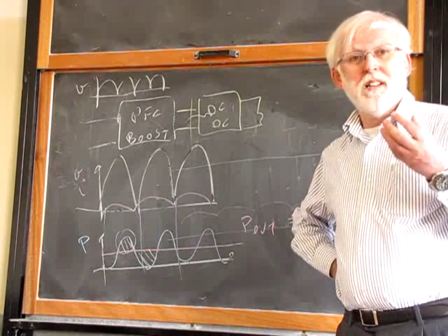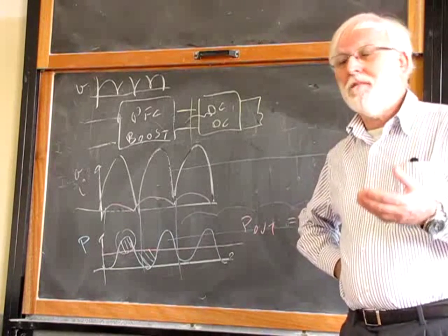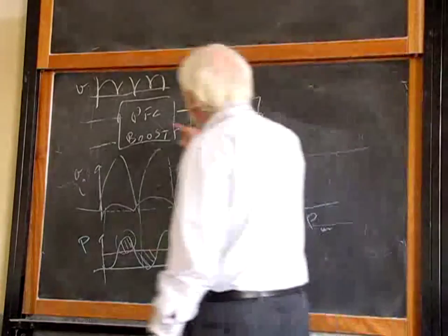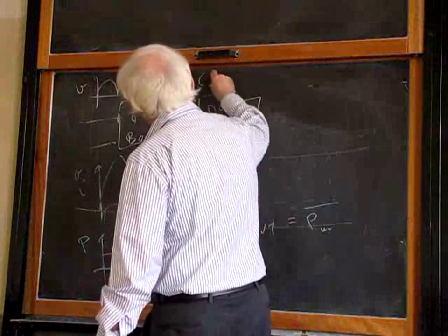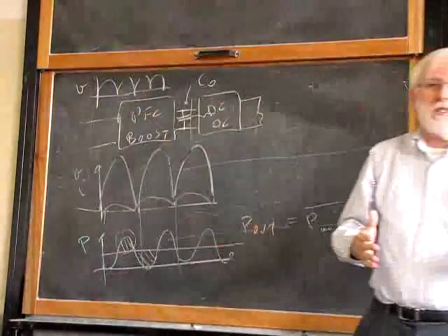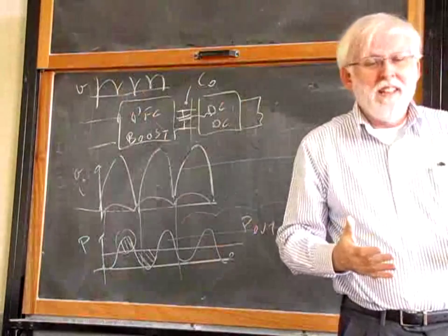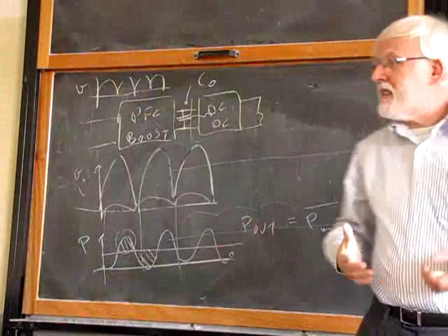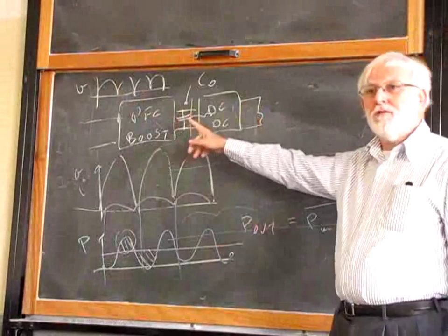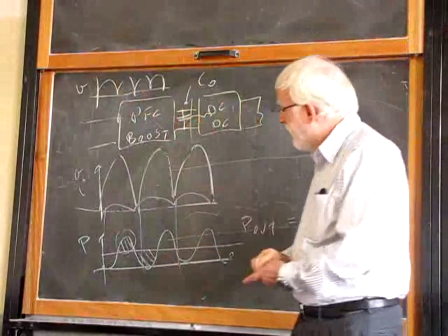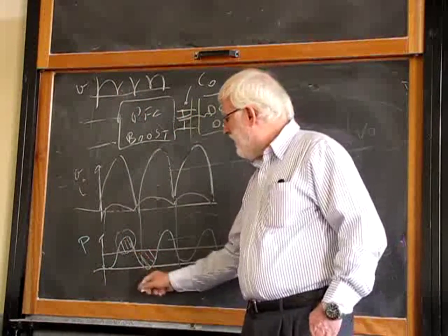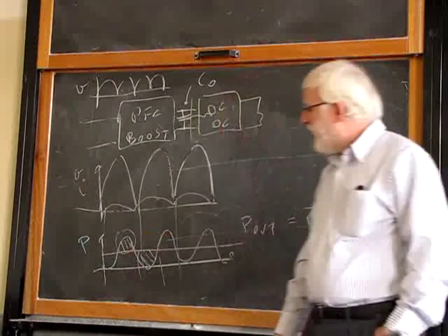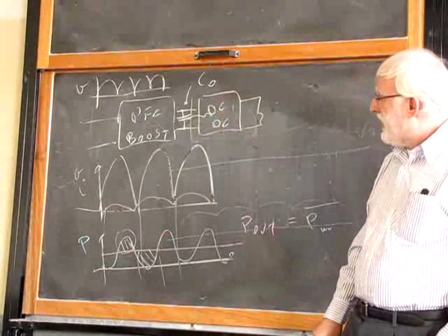Capacitors are smaller, less expensive, lighter, etc. So, PFC circuits have here at the output a capacitor that must be there because it's a boost converter, but this capacitor is also used to store energy and to release it shortly after it got the extra energy.